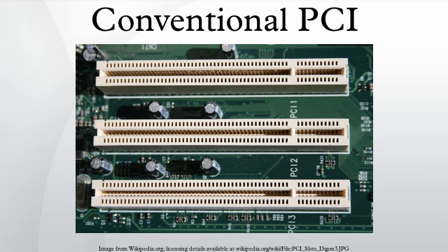The PCI SIG strongly encourages 3.3 V PCI signaling, requiring support for it since standard revision 2.3, but most PC motherboards use the 5V variant. Thus, while many currently available PCI cards support both, and have two key notches to indicate that, there is still a large number of 5V-only cards on the market. The M66EN pin is an additional ground on 5V PCI buses found in most PC motherboards.